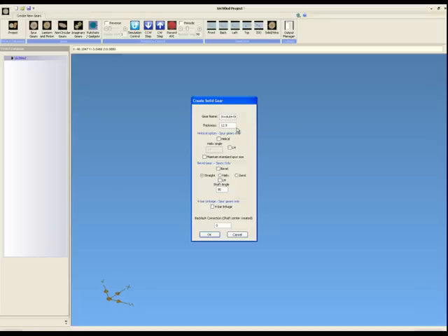Thickness of the gear is just that, the actual thickness of the gear going from the front to the back. You can see mine is defaulted to 12.5 millimeters, for example, this being a half an inch and exactly the size of the plywood I typically use to cut gears from. The system will remember this setting. Each time that you set it and say OK to this dialog, that number will be changed. So if you're frequently changing the thickness of your gears, you might want to check that each time. If we don't push anything else on the screen and we simply hit the OK button, we'll end up with a Spur gear on the screen.